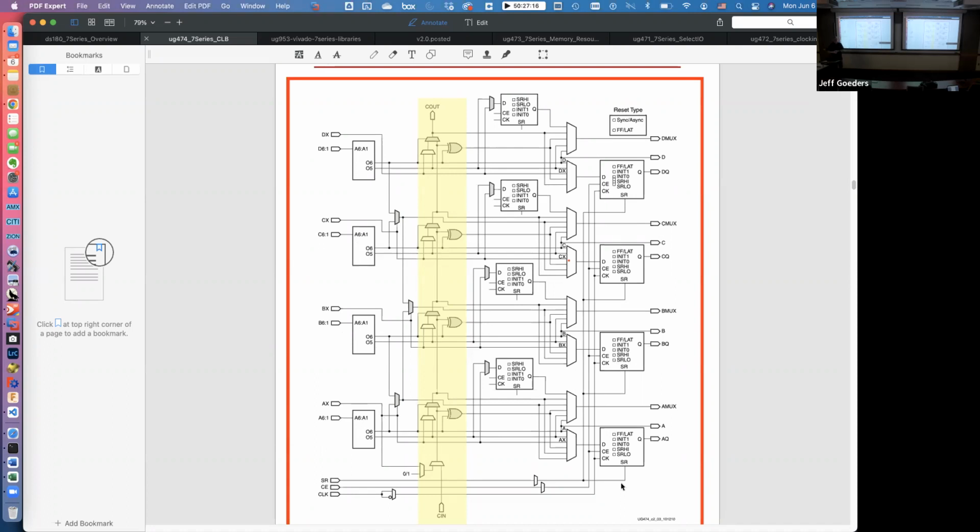What's this other gunk in the middle? Well, the early Xilinx parts had 1 flip-flop per LUT. And as Dr. Goeders said, and I agree, they're constantly taking user designs and looking at the contents of designs that their users share with them to see, hey, if I added some extra flip-flops inside every slice, overall, would that help their circuits be smaller and run faster?